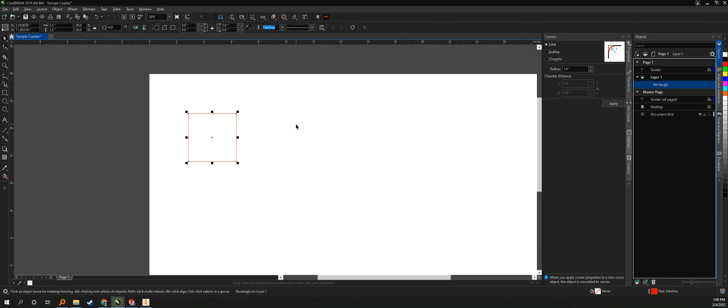Now a good thing you can learn is the corners. If you go under here, you'll find corners. Different types. So if I want a rounded corner, I'll click fillet. If I want a straight corner, I'll click a chamfer. Today I'm going to do a fillet with a 1/4 inch radius.